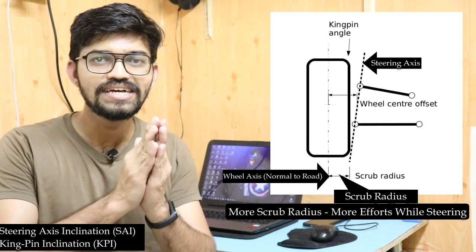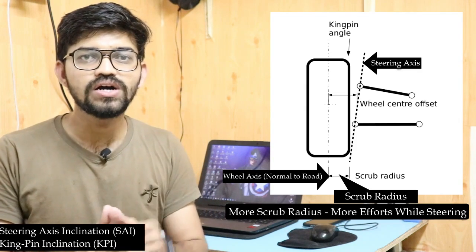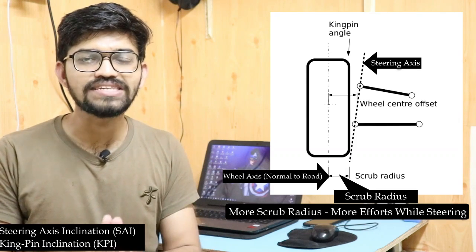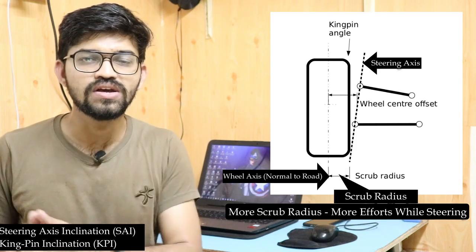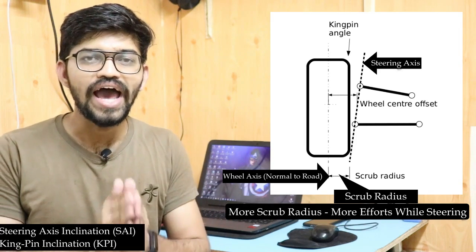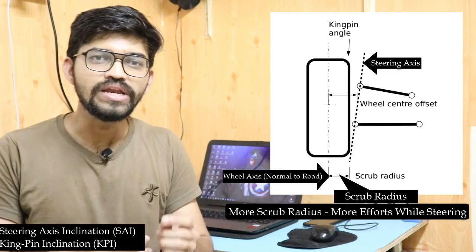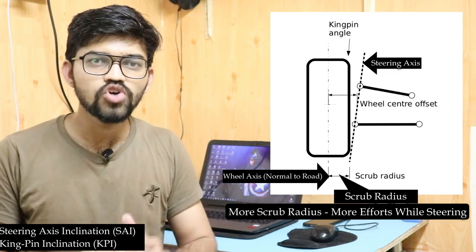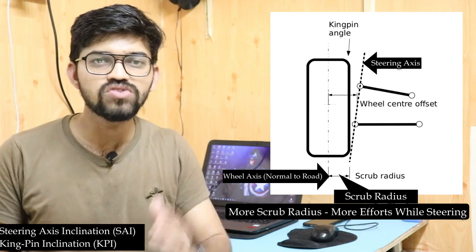steering axis is slightly inclined to the axis of the wheel, and this particular angle which gets formed over here is called the kingpin inclination or the steering axis inclination. This kingpin inclination helps us to reduce the effort while steering and to increase the stability of the vehicle. Also over here, another important parameter is the camber of the wheel.